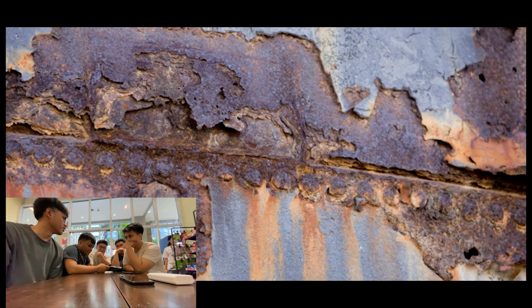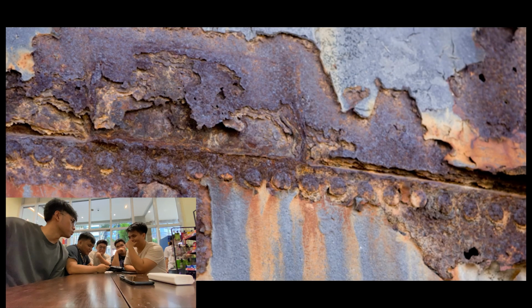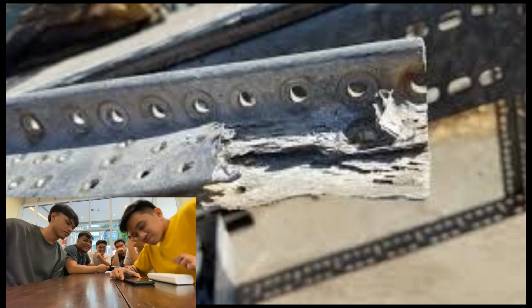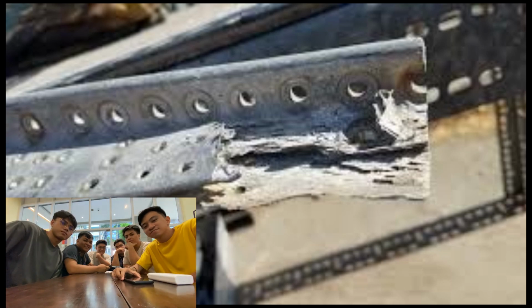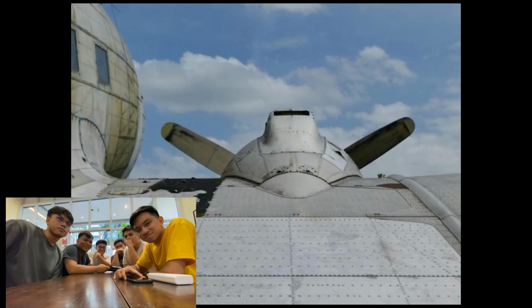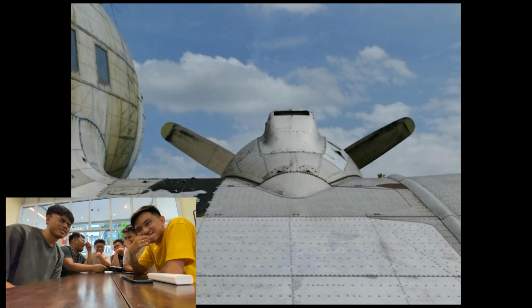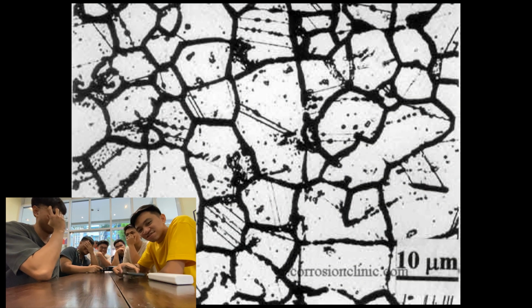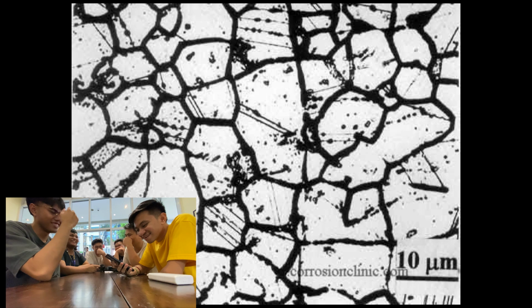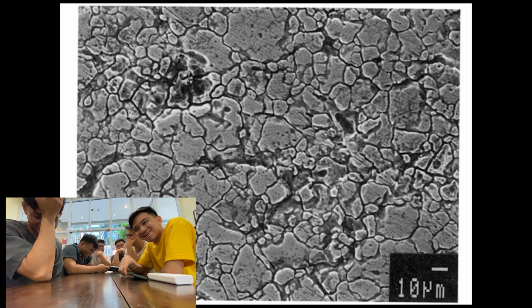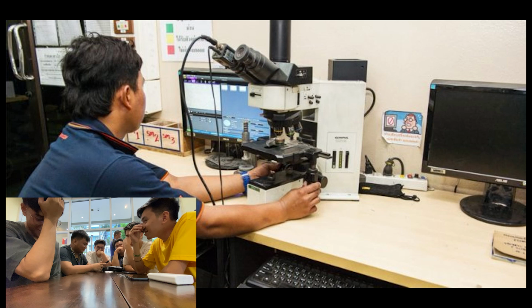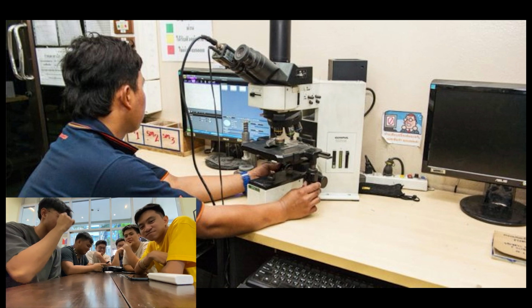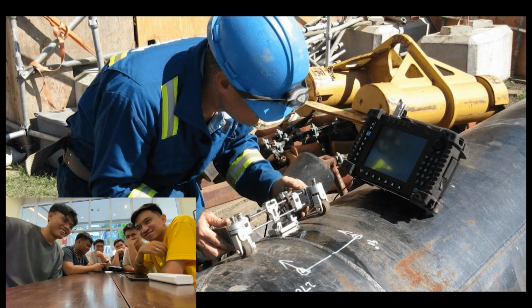1. Intergranular corrosion. Intergranular corrosion occurs along the grain boundaries of an alloy. It's common in stainless steels and aluminum alloys. Causes. It typically happens due to the depletion of protective elements like chromium in the grain boundary areas during improper heat treatment. Detection. This can be detected using techniques like microstructural analysis or electrochemical methods that reveal the weakened grain boundaries.